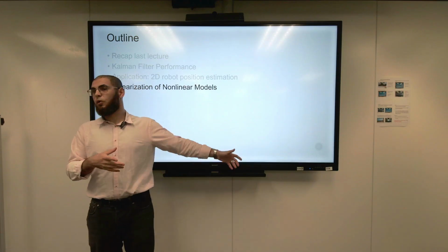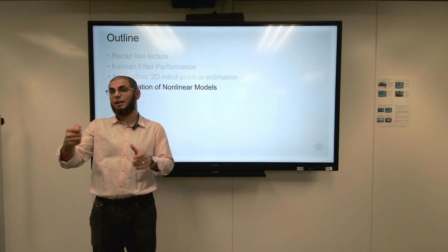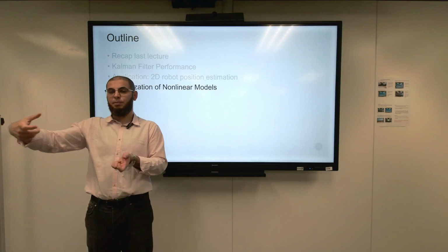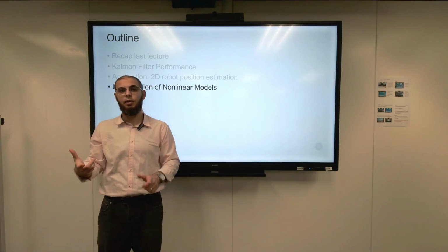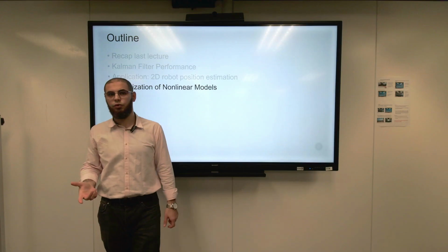And you remember when we had the experiment here in the lab and Tariq was playing around with the IMU, you saw that it was very accurate. It was not being affected, for example, when Tariq moved his phone or moved something that was metal. It was not affected by that. So the PX4 was actually already implementing a Kalman filter for you.